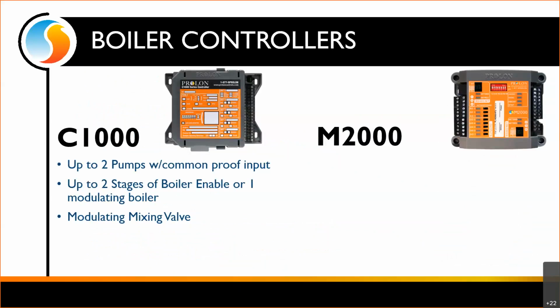So transitioning the boilers over into those 2 hardware options that we have, the C1000, the M2000. On the C1000 side, we can do up to 2 pumps with a common proof input. So that would be like your flow switch after the pipes reconverge when you split to go to your 2 pumps. So we only have a single pump proof. We're also going to be limited to 2 stages of boiler enable or 1 modulating boiler on that. We can still do the modulating mixing valve, but this is going to be for your smaller setups, the C1000.